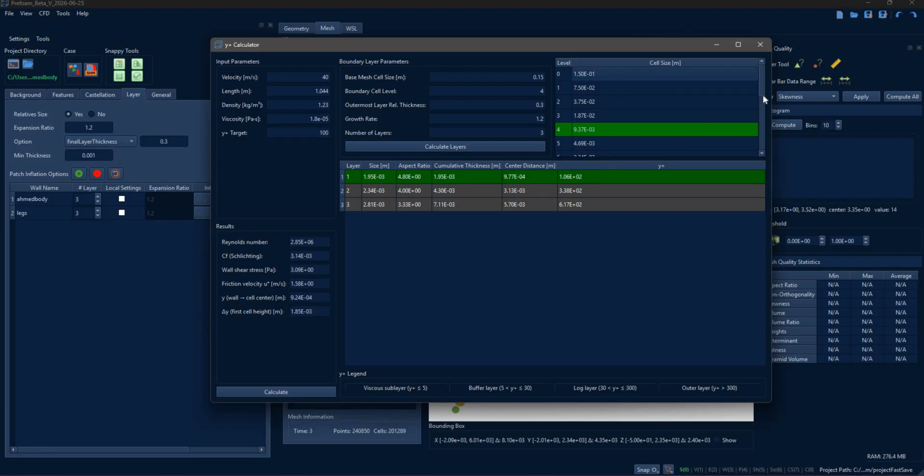And then in this table you have your level, your base mesh is 150, so you will have 150 over here, and then these are the refinement levels and the size of this. And at the surface you will have like 9.37 millimeters, and we said that we have 0.3 as factor, so the size of the outermost layer will be like 1/3 of this value.